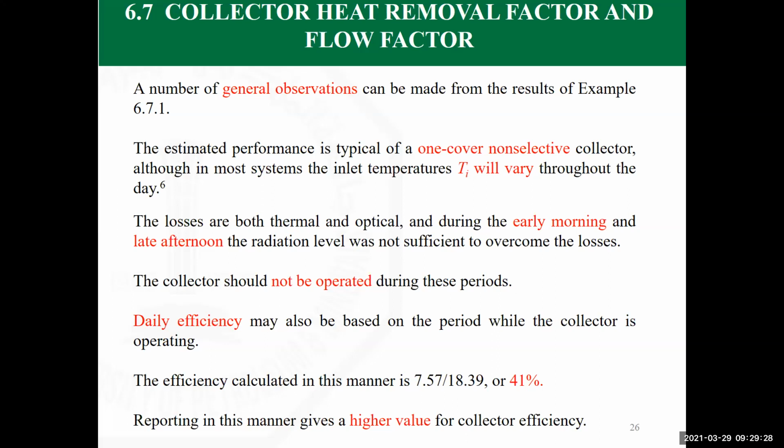The losses are both thermal and optical. Early morning and late afternoon, we have high losses. The amount of energy coming from the solar is not enough, and this is why we talked about the issue of critical radiation: below a certain value of the radiation flux, you turn off your collector. You don't need to pump the fluid in because you are going to lose energy.